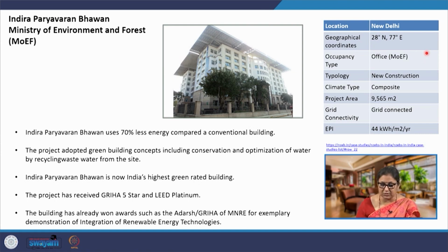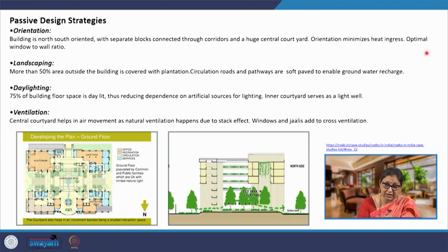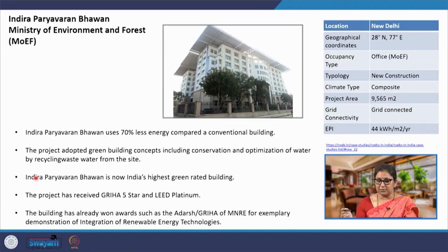Lot of strategies have been used. So, what they have done is designed this building in a manner that there is open area. So, this is the landscaped area that they have created. There are 4 towers which go to G+6 floors above, and they shade this landscaped area partially. And on top of this entire building, as you can see in this picture, they have extended the frame to support the photovoltaic cells, the solar cells, and it acts as a second roof, a shading roof on top of this entire structure, which shades the landscaped area as well as the building part.